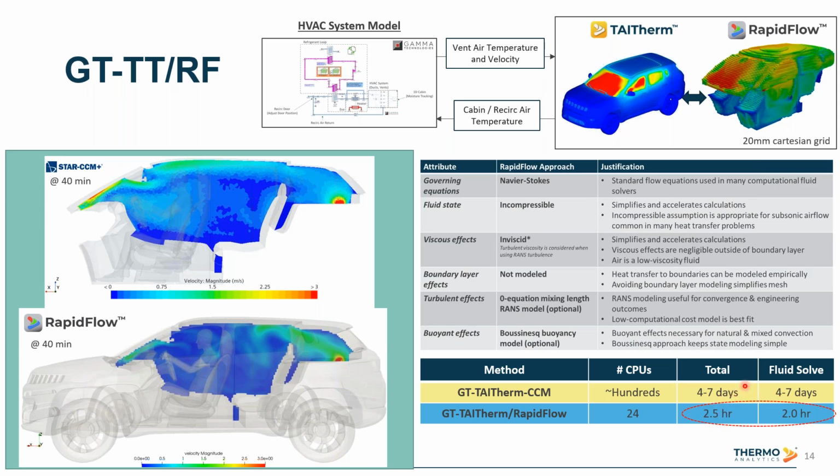The bottleneck here for this 3-tool coupling is CFD. So running 40 minutes of CFD in real time can really take some time. Of course, there are some simplifying assumptions, like I mentioned. So the speed up is nice, but we do also have to compare the results in detail shortly. You could see some initial velocity contours here. One is from ParaView, one's from Star CCM. So the scale's not exactly apples to apples, but you could see similar flow field behavior.